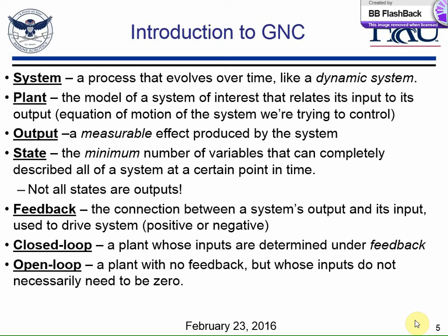Those 3 states are what we call your kinematic states. Now you also have 3 more dynamic states. Do you guys know what those are? Your speed, right? Your body velocities, right? So you have 2 linear velocities and you have 1 angular velocity when you're dealing with surface vessels, right? You have your surge velocity, your sway velocity, and then your yaw rate.